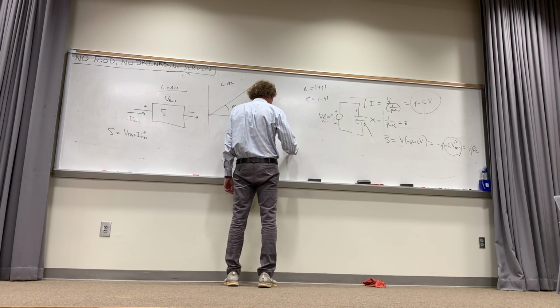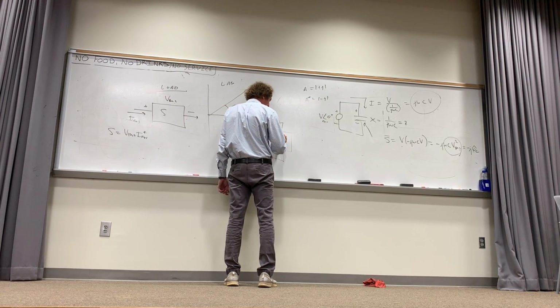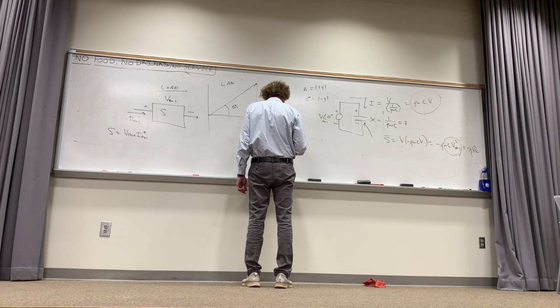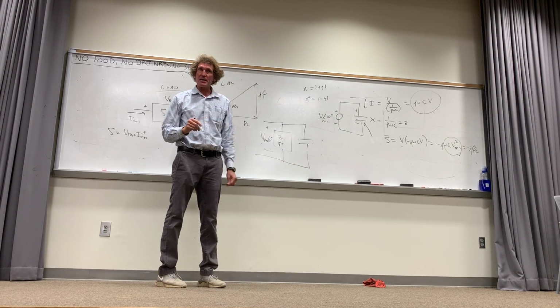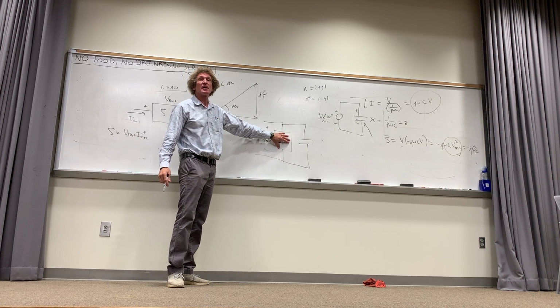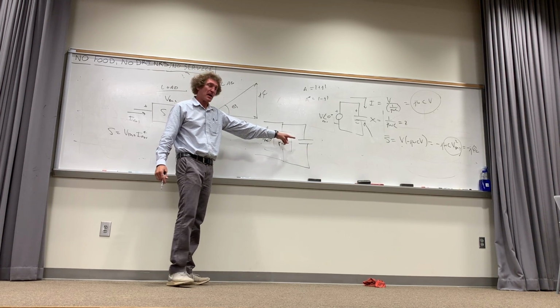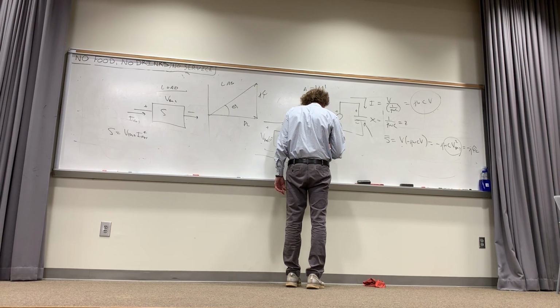So if I take a net load like this, that has a plus to minus VRMS at 0 degrees across it, and I have a Z load here with a certain power factor, and it has a lagging current, which means S is in the first quadrant, then if I add a capacitor in parallel with it, the capacitor's complex power is minus J omega C VRMS squared.